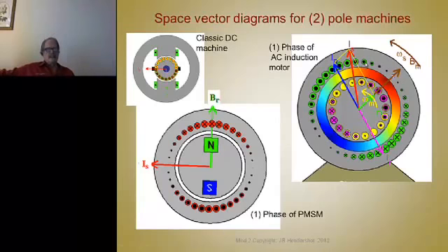And in the case of a two-pole motor at line 60 hertz, the RPM of that stator field would be 3,600 RPM. 4-pole would be 1,800 RPM. 8-pole would be 900 RPM. A mathematical relationship. But the actual rotor doesn't go that fast. It goes slower than that. It has to go slower than that.